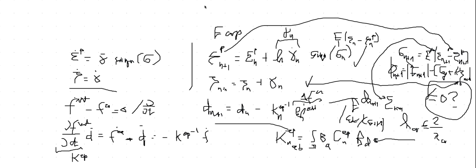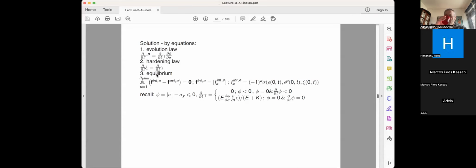One can though try a compromise to have something like implicit on this one and explicit on that one, which is kind of good, because when we had the job, after the World Trade Center attack, of verifying the security of some kind of nuclear installation for the French army, we did a very complicated model of this, crashing the airplane and stuff like that. Basically, the idea is that we did this one explicitly because it was impact and frictional contact, and this one was done implicitly, so you can have a stress admissibility. But that's the compromise. If you really want to go safe and sound for everything, you go for the implicit scheme.